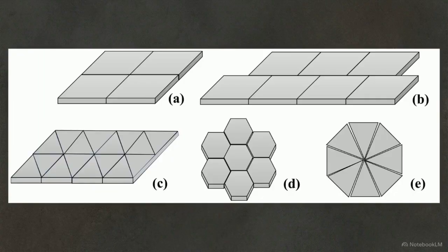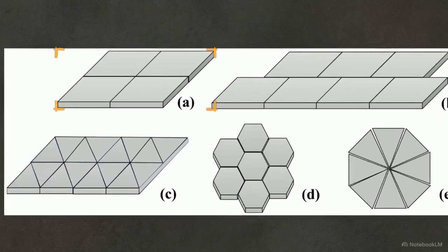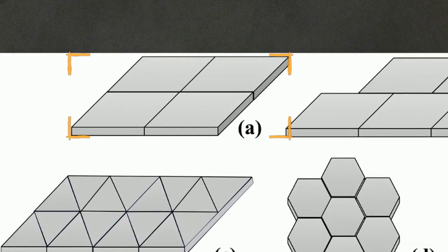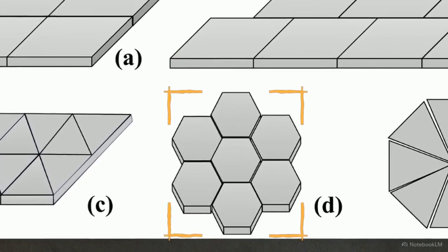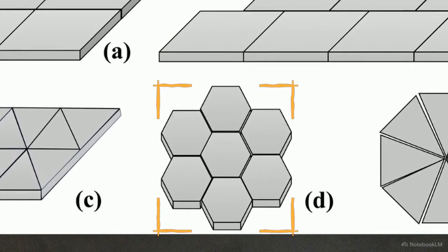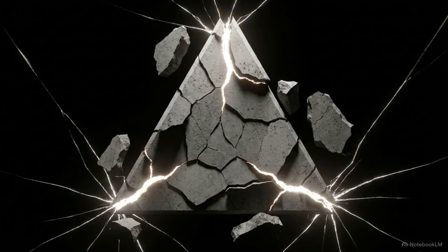This shows how we assemble these units into a continuous surface. A square grid aligns its seams, creating a continuous straight-line path for cracks to propagate. The interlocking honeycomb splice, however, naturally disrupts these continuous stress paths. The data proves that a high-strength design like the triangle destroys itself. The only geometry capable of surviving long-term vehicular dynamic loading is the low-strength, high-stability matrix of small-scale hexagons.